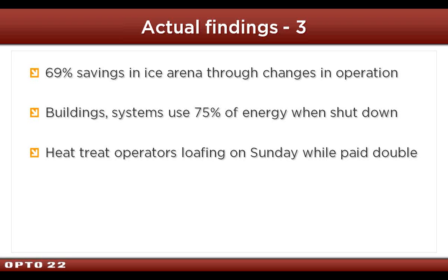We found buildings that supposedly were shut off that were still using 75% of what they were when they were in full operation. I spent a lot of nights going around opening up electrical panels with clamp-on ammeters trying to find loads. You go into a building where they say everything's shut down, all our equipment's down, it's down for nights or weekends or vacations, and then you get the data and it shows they got a 500 kW load in there somewhere. So, just waste.